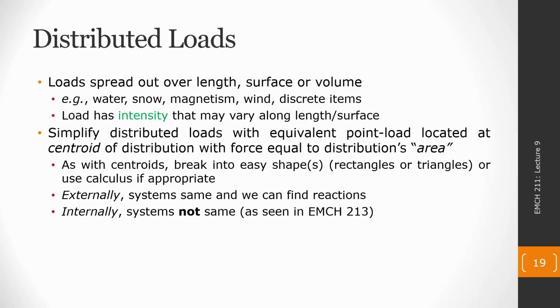So if the loading has a functional relationship, that we have some intensity that varies along the length and we know the algebraic relationship between the two, then we can use our calculus, our one-dimensional integration steps, like we did for finding the centroid.